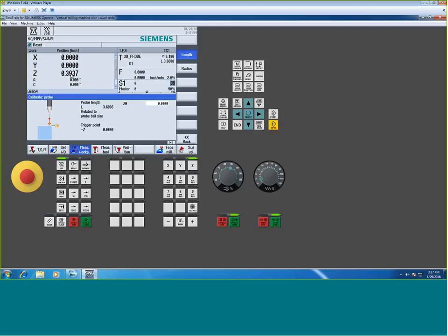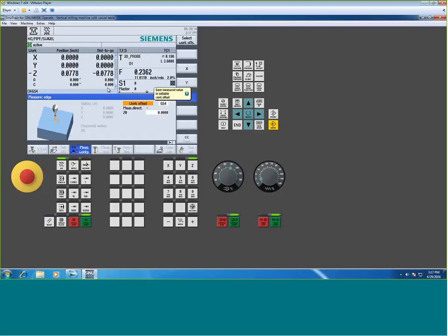So here, I was close enough to 0 within this pick distance that it wouldn't think that it didn't make the probe. But once you've done this, now this probe's fully functional. So now you can go into any of the measuring cycles and any of the axes, cycle start, and it'll mimic if it was running a probing cycle.